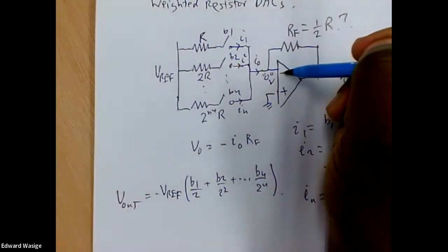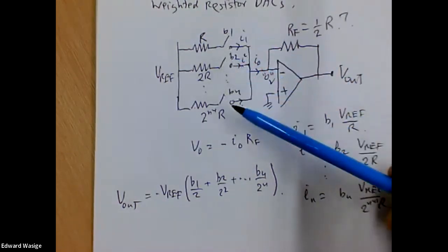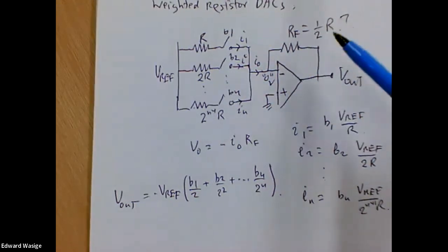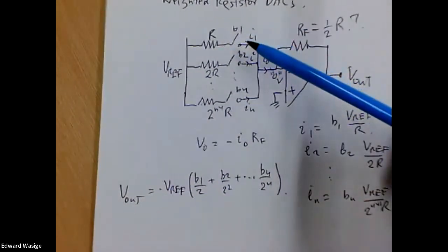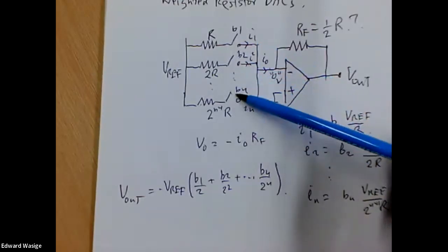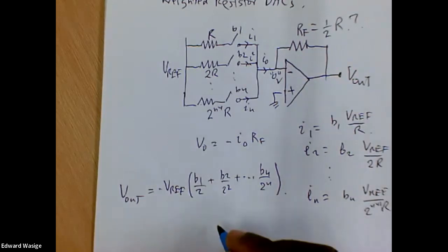So with an op-amp in summing configuration, it's quite easy to make a simple DAC. If we have digital inputs B1, B2 up to Bn, we just need to construct this circuit. We know how to do the op-amp. The MOS devices can also be used as switches, as you know. So we know how to do that. We can realize the resistors, and there we have our DAC.